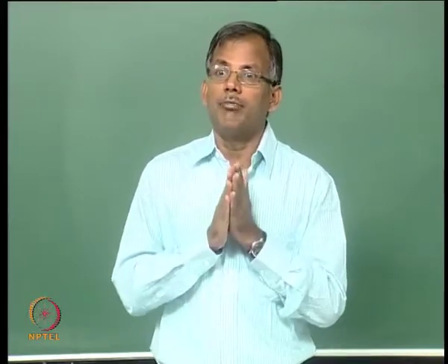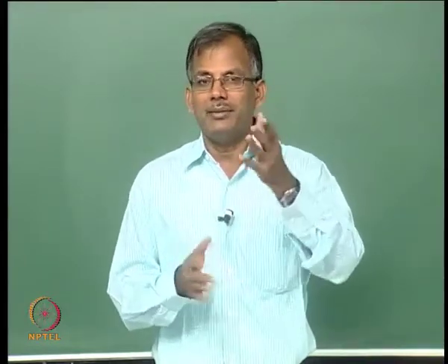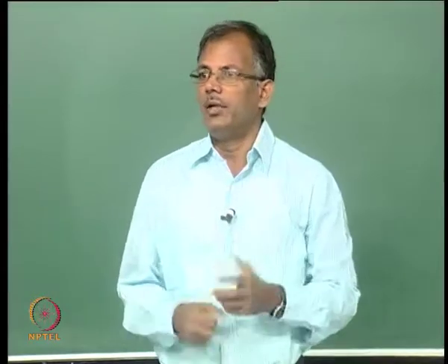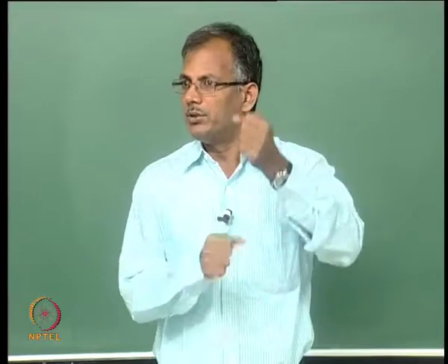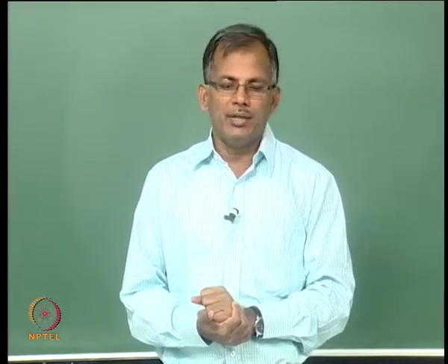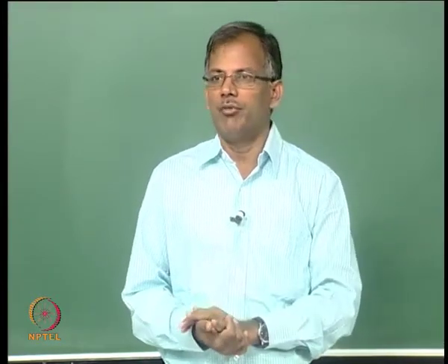No other forms of failure are going to happen, because if you imagine a member in full tension, neither global buckling nor local buckling is going to happen, because it is under tension. That makes the calculation for tension very simple.